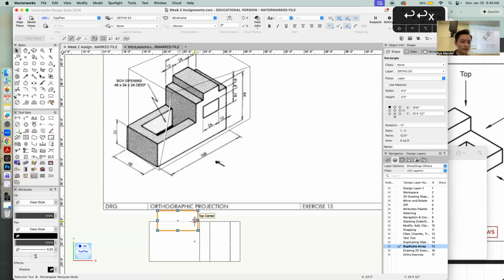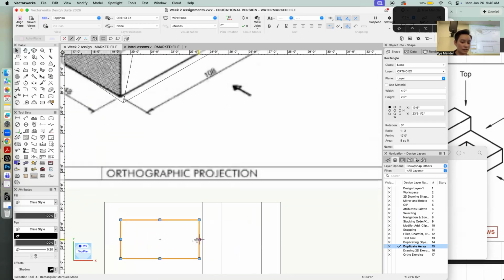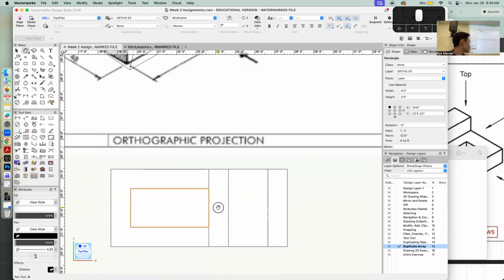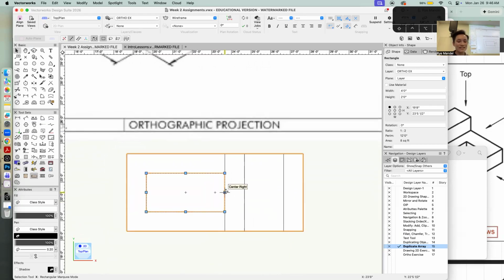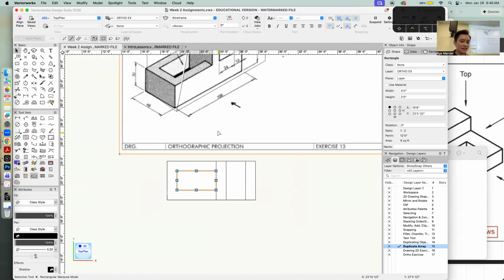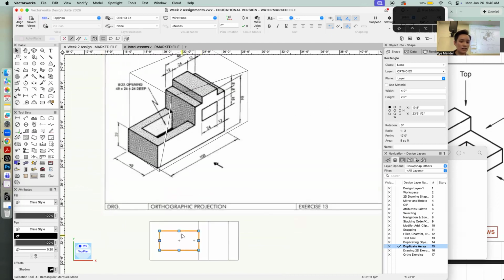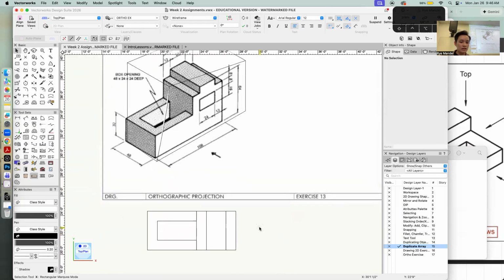So a way that you can do this is click on the middle and then hit this under where you snapped it, and it'll bring it to your center where it says midpoint. It'll have a little glass that says midpoint. Sorry, y'all can't see it. It'll say midpoint. And then that's how I know that this is centered and that it's correct with everything else. So that is how I would do the top view.